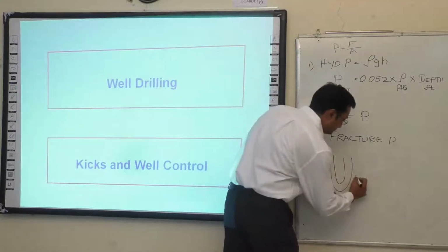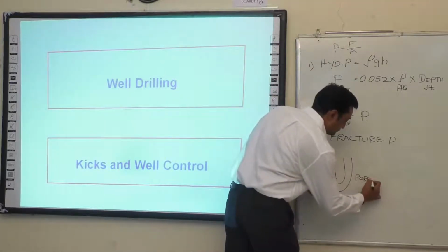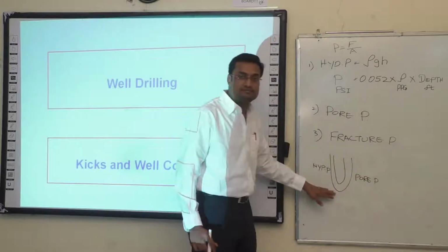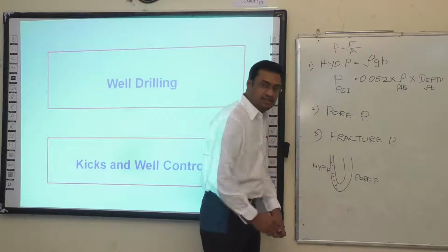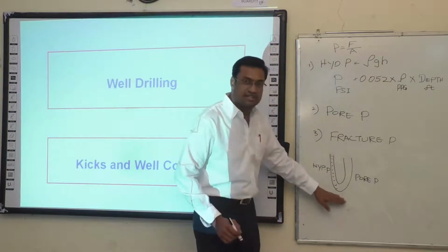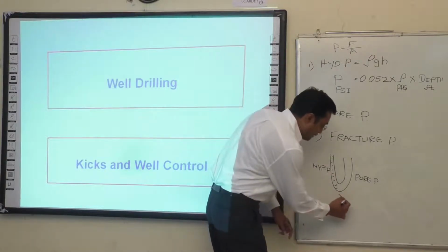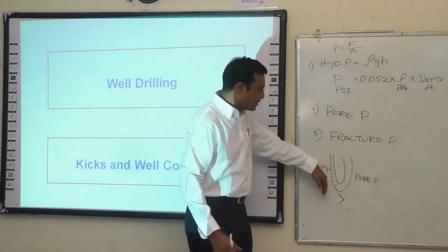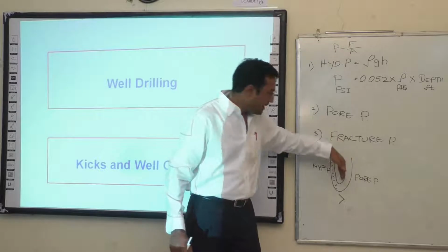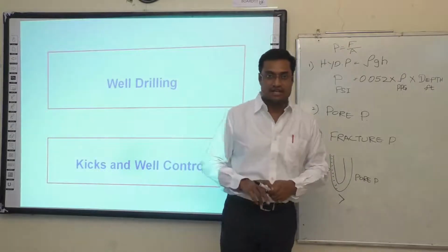This is the pore pressure. Because of the drilling fluids, the hydrostatic pressure is more than the pore pressure. That is called overbalance. The well is in overbalance condition.